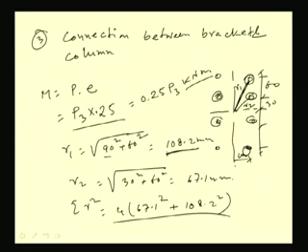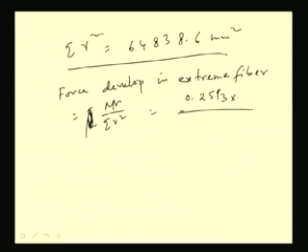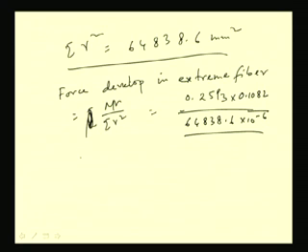Okay. So, R1 is 108.2, so we can make it 0.1082, this is in meter, by summation R square, 64838.6 into 10 to the minus 6 meter square. So, after calculating this, we will get 0.417 P3, right. So, force developed in extreme fiber due to moment is this much.